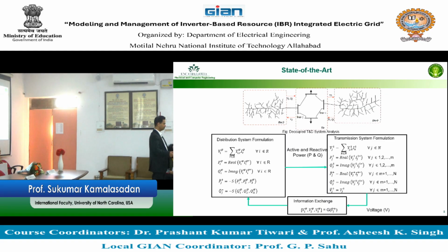You solve for voltages and angle of the voltages, right? These are the states in the power flow. Then you calculate the power, then you calculate the losses, then you calculate the power flow. All those things are unwound if you know the voltage and angle of voltage, right?